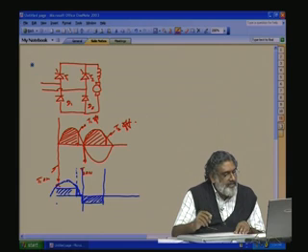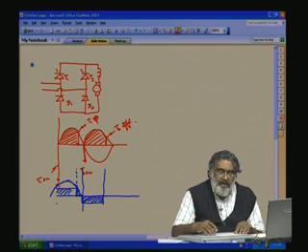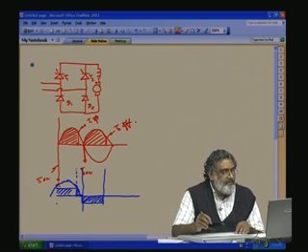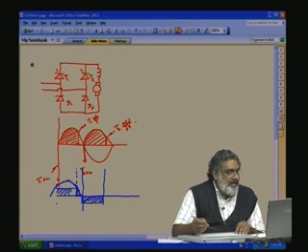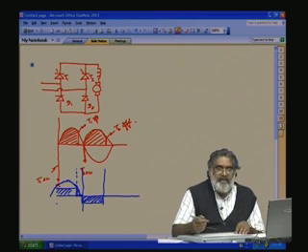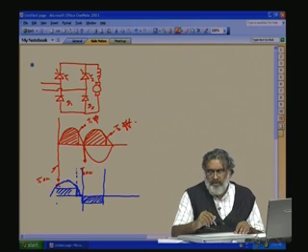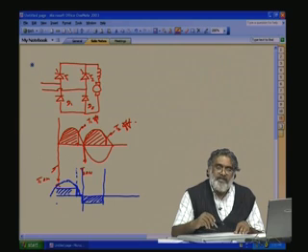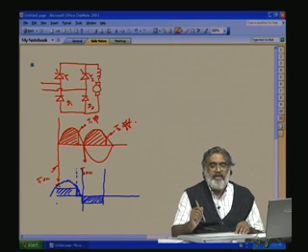This is another advantage of these 2 degrees of freedom. Here the fundamental supply current leads the voltage, so the displacement factor is leading, and as I told, this feature may be desirable to compensate for line voltage drops in power systems. What I want to bring here is that we have 2 degrees of freedom: whenever we want, we can turn on the device, and whenever we want, we can turn off the device.